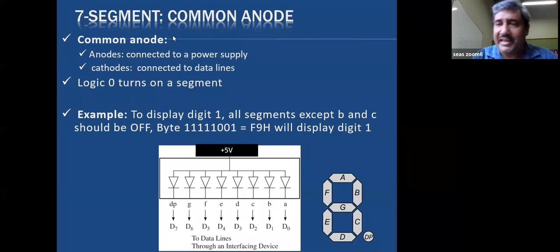Okay, you have the diagram before you. Can you type in binary, right? All 8 bits, which 8 bits will you send out to turn on these segments? Everyone, can you type please? Right. So remember, logic 0 will turn on the LED.